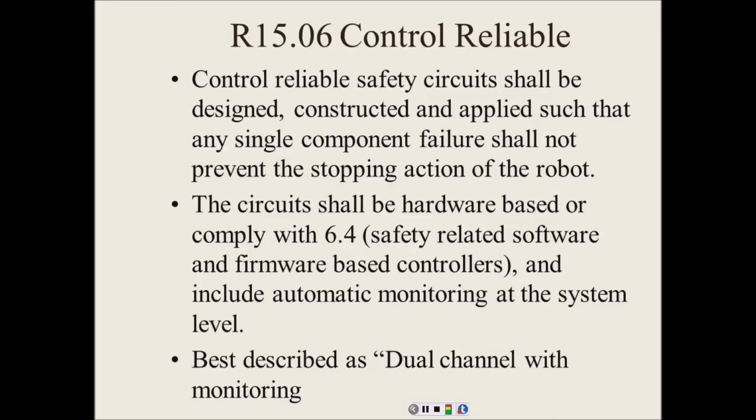Hardware means you got to be able to touch it. So an e-stop button cannot be a little touch button on a CRT somewhere. You can't do it because that's controlled by software, right? You understand? E-stop buttons have to be hardware. They cannot be computer based because computers have problems. Computers lock up. Well, what if your computer locked up and you can't stop it? The e-stop button on your little old touch screen doesn't work anymore. Now, we do a lot of stuff with those computer screens, but your safeguard and your e-stop circuits have to be hardware. They have to be mechanical.